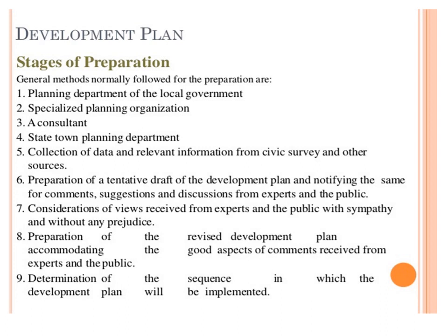Then preparation of tentative draft of the development plan and notifying the same for comments, suggestion and discussion from expert and the public. Then consideration of views received from expert and the public with sympathy and without any prejudice. Next step is preparation of revised development plan, accommodating the good aspect of comment received from the expert and public. And finally, determination of the sequence in which the development plan will be implemented. These are some stages of preparation of development plan.